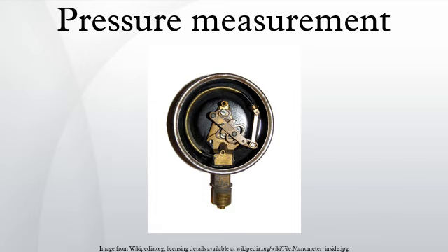A vacuum gauge is used to measure the pressure in a vacuum, which is further divided into two subcategories, high and low vacuum. The applicable pressure range of many of the techniques used to measure vacuums have an overlap. Hence, by combining several different types of gauge, it is possible to measure system pressure continuously from 10 millibars down to 10^-11 millibars. Absolute, gauge and differential pressures, zero reference: everyday pressure measurements, such as for tire pressure, are usually